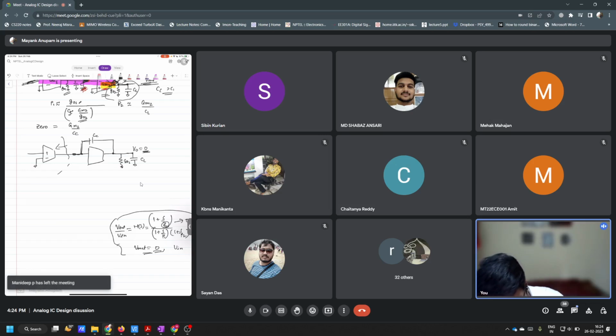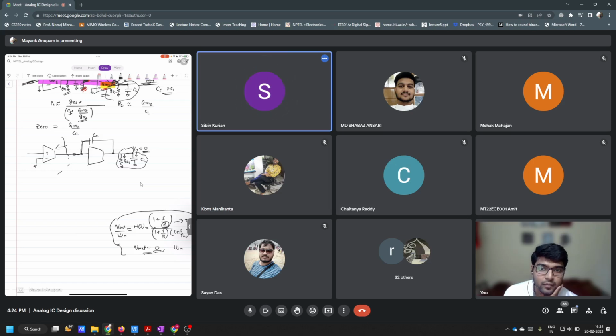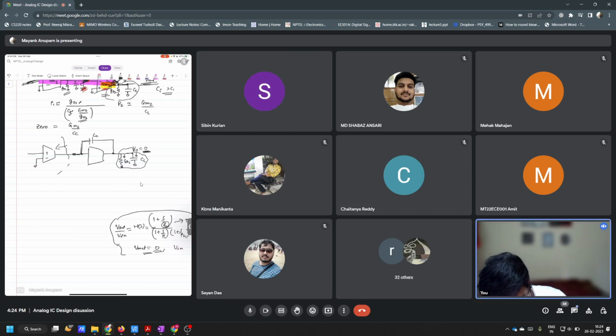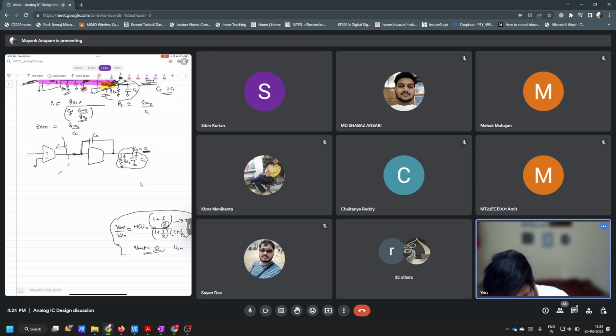If the voltage is zero here, no current can go inside, right? Current flowing through these two guys will be zero, correct? I mean, there is no ambiguity in that, right? If the voltage is zero across any element, current passing through that should be zero. It's a linear element, so voltage is zero, current is also zero, right? Yeah, Ohm's law. Correct.